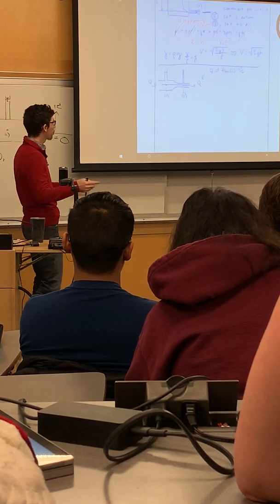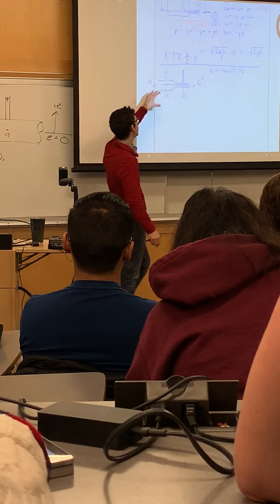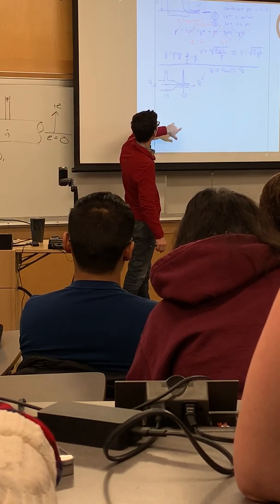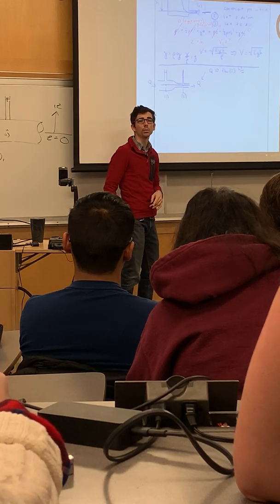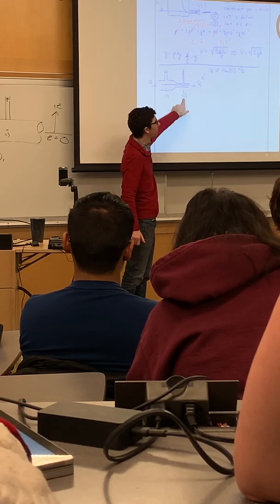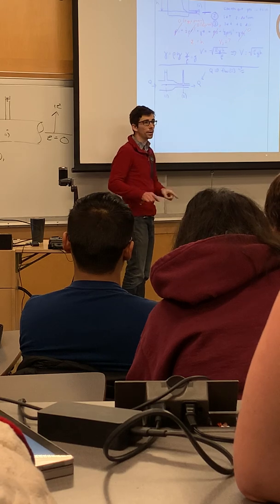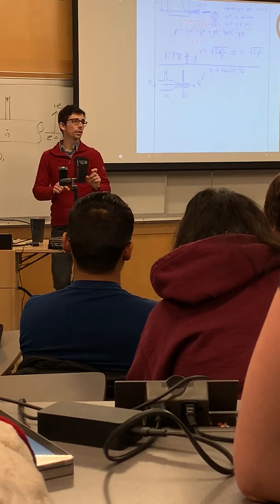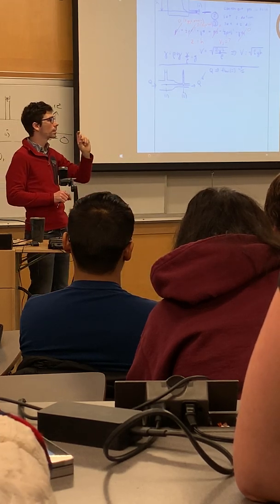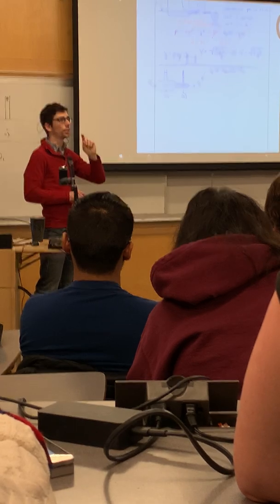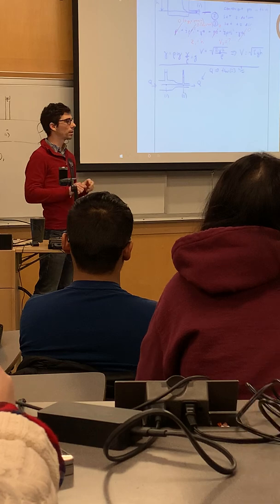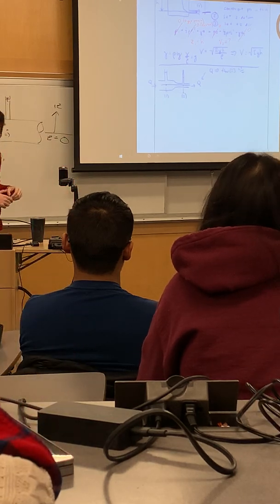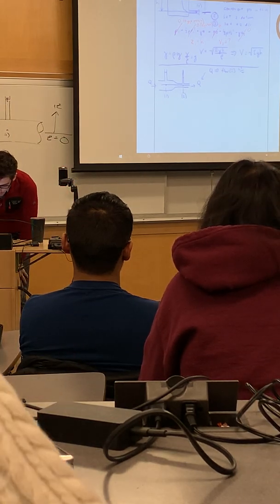And so if the elevation were changing in this example, we account for that by saying Z1 and Z2 don't equal. In this example, Z1 equals Z2. But in either case, the static pressure is still the measurement of the piezometer, which is the specific weight of the fluid times the height in that piezometer. Okay?